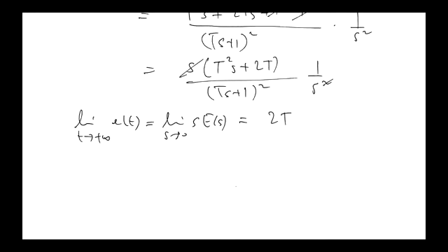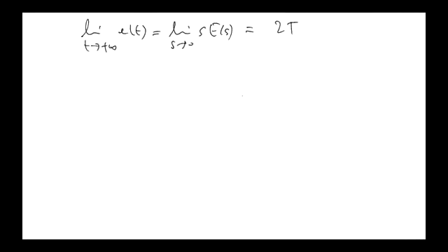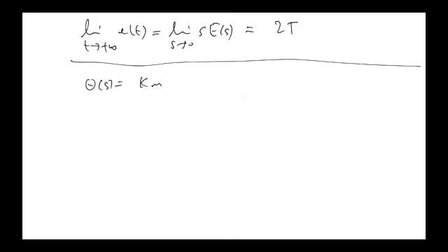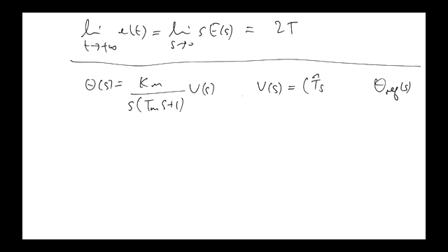All right. So let's suppose that for our controller, we've got our motor model, right, with parameters that are roughly right, but not exactly right. And I'm going to choose my voltage input to be related to the reference for theta, such that I use a slightly different model to invert.